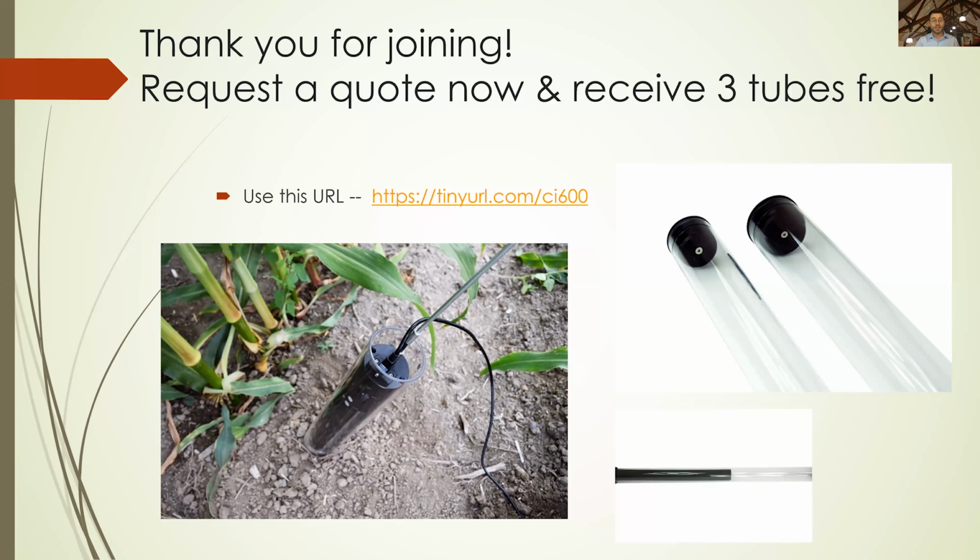And the next one is how sensitive the cameras are to soil types. Actually, the camera itself, as long as you're making sure that the scanner head is up against that acrylic tube and the acrylic tube's not deformed or scratched up itself, is very, very sensitive and able to pick up your different soil types. You can see each one of the visible scans. So you can see very rocky, very sandy, very clay, as I typically find where I'm usually from. But you can definitely pick that up pretty readily with the scanner.